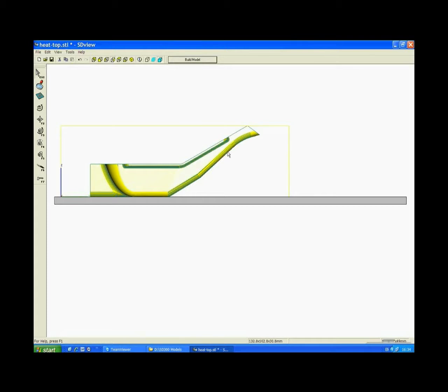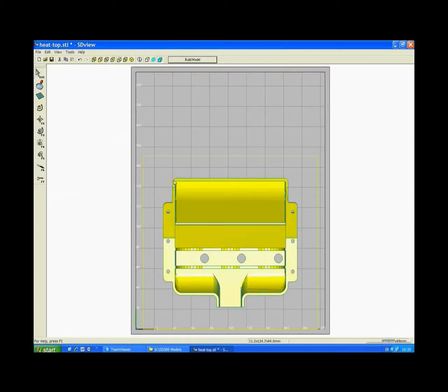In order to make sure this part can be peeled in sections removing support material up or down, we will break the diagonal feature in this model into sections using peeling cuts, making sure that the support material going around the part will be cut with a peeling cut. To do so, again we will go to the top view and run peeling cuts in the center of these walls here, and again for the other side.